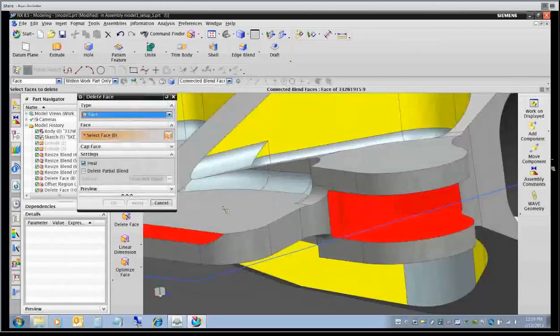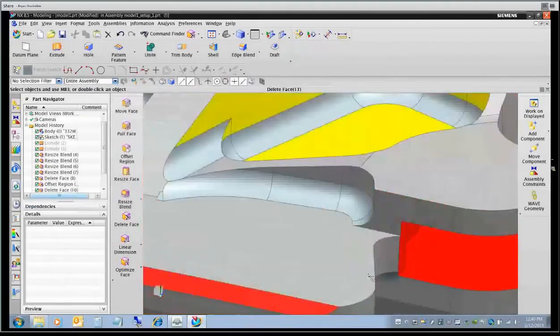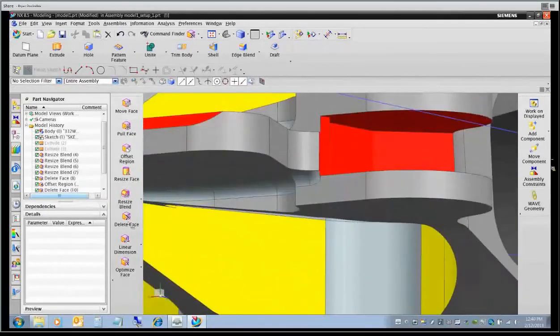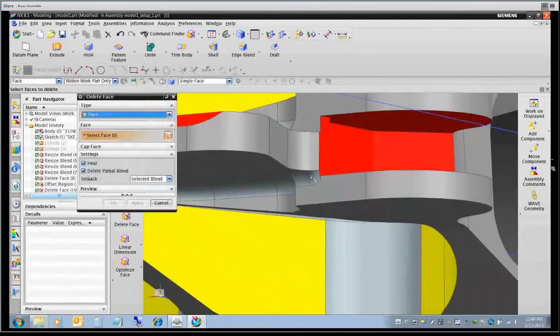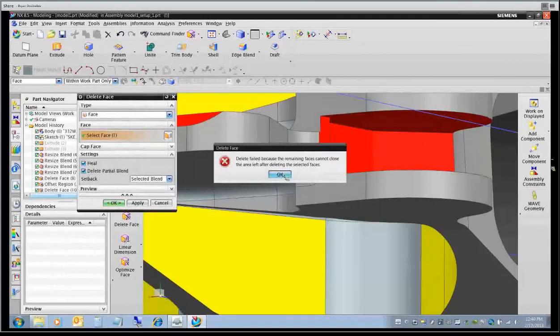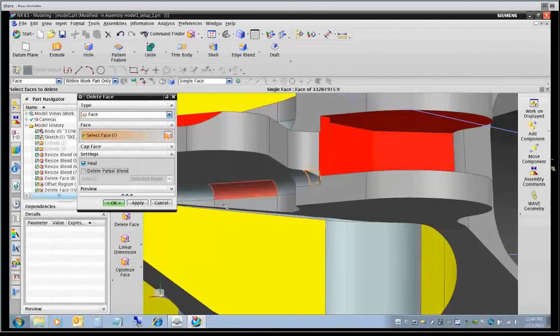And by picking this with that partial step back, you can see what you're doing on each step, of what that feature was, the intelligence, the way we're understanding the topology of the part as it goes through there. Again, there's a little blend corner on the bottom. You may want to remove him, so we can take a look at the overall. Again, we say single face, and we're just going to go ahead and delete this guy.